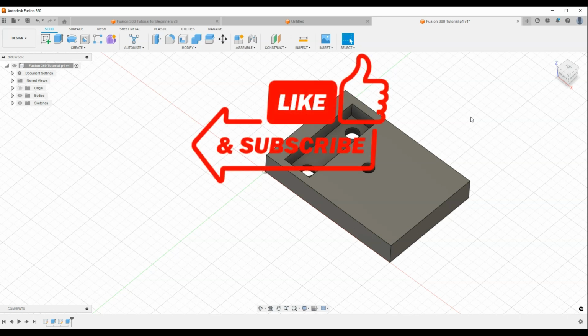And in the next part of the guide you will learn another operation of creating 3D solids based on a 2D sketch and another tool for creating 2D sketches. You will learn the operation of creating a 3D solid by rotating a 2D sketch, and with this operation we will create the next stage of this 3D solid, and you will also learn how to create a reference plane on which we will create a sketch. Reference planes are very helpful in designing complex projects.